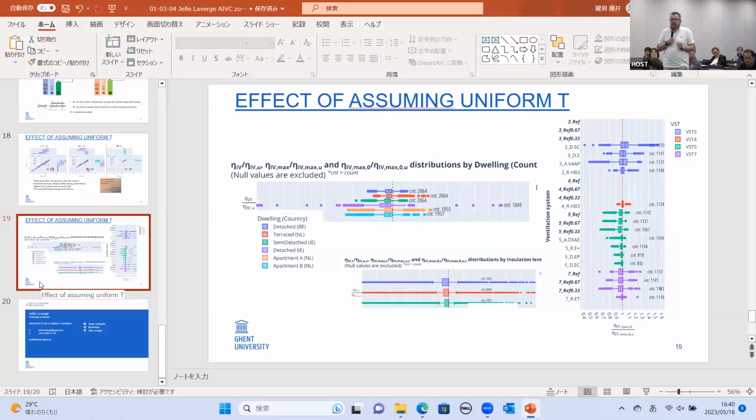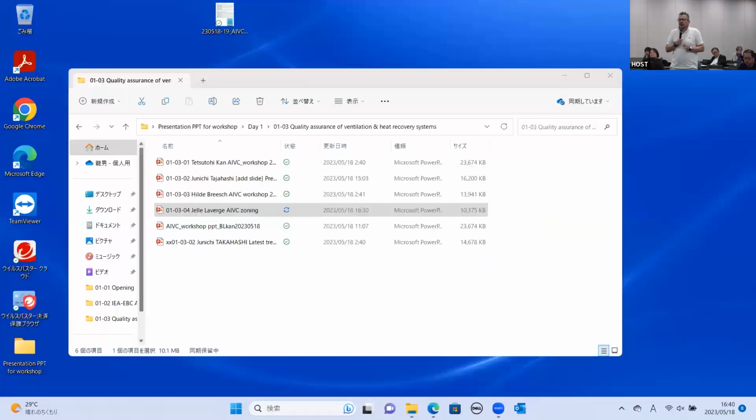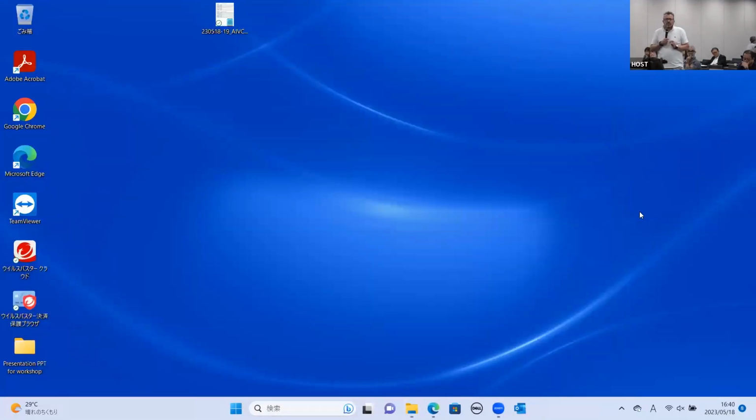And here you have a hidden moisture transfer, and you use a paper as a material for your heat recovery. Have you documented that there is no transfer of the pollution between the extracted air and the supply air? And if there is any transfer, what type of pollutants are transferred and at which rate? I ask this question because this type of solution is becoming popular in Europe as well.